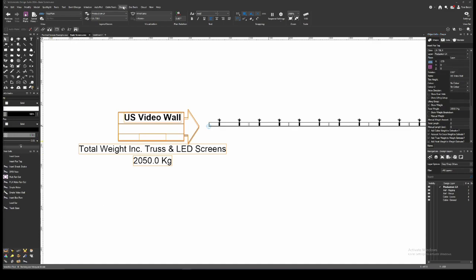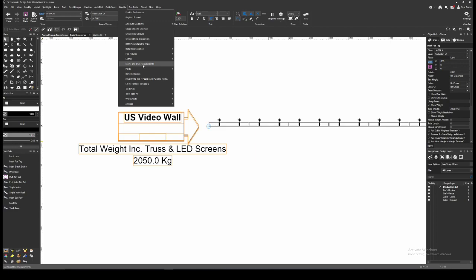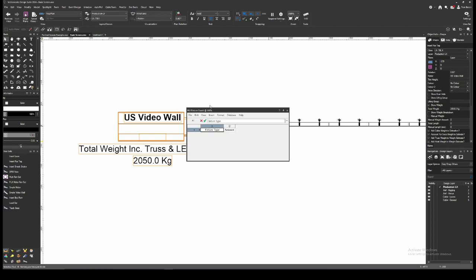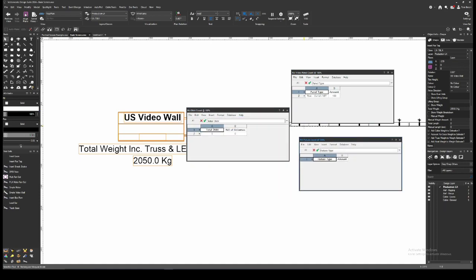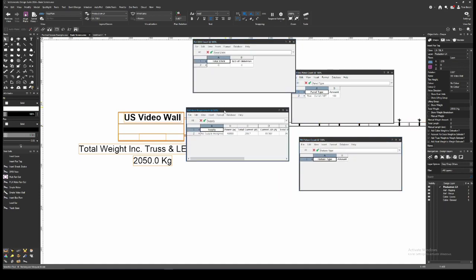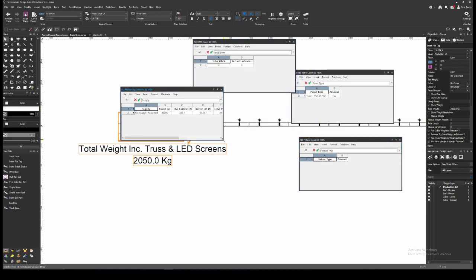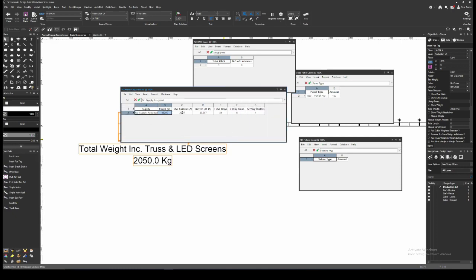Simple Video is also compatible with the mains and DMX requirements command. If we run this command, it will tally up the total power requirements for both lighting fixtures and simple video objects in the document, and will then give us a total power requirements for the document, as well as a panel count of how many panels of what type are in the document.